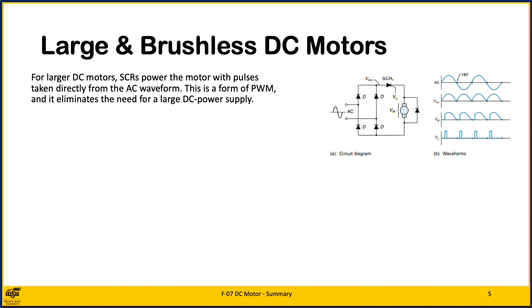For larger DC motors, SCRs power the motor with pulses taken directly from the AC waveform. This is a form of PWM, and it eliminates the need for a large DC power supply.